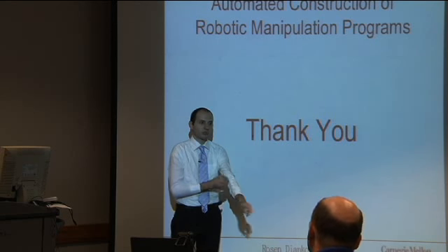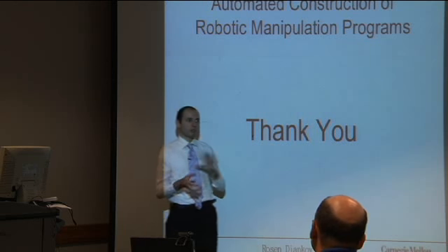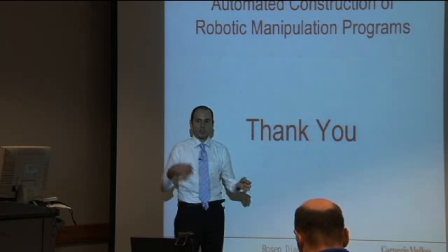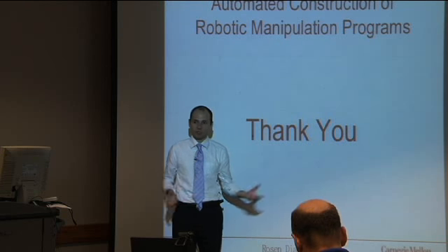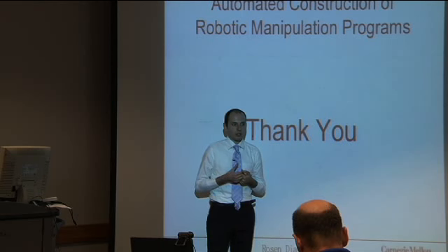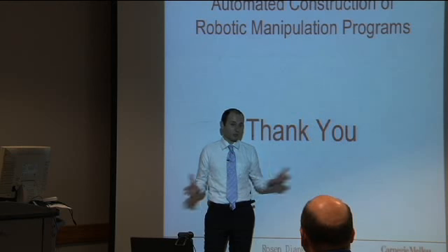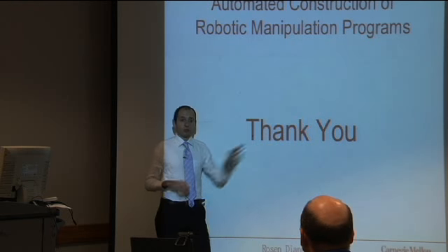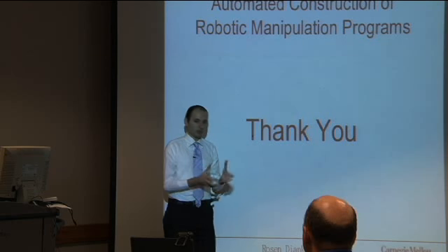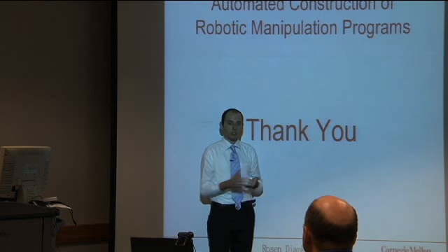In fact, that's one of the reasons why in the end we chose a repeatability measure. There were other measures, for example, earlier attempts to reject grasps that attempt to compute force closure and evaluate the measure after disturbances have been computed. This rejects a lot of the grasps for anthropomorphic hands like the Barrett hand. For example, 80% of the grasps would be rejected. And for a 1 degree of freedom hand, using these earlier measures, 100% of the grasps would be rejected. Whereas with repeatability, because you can adjust the threshold,